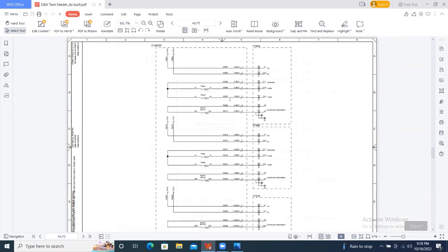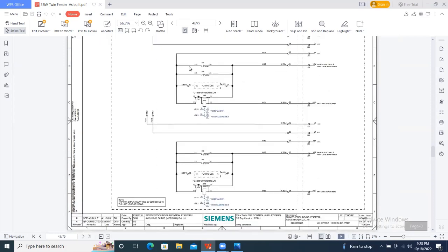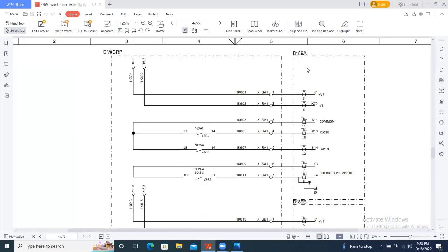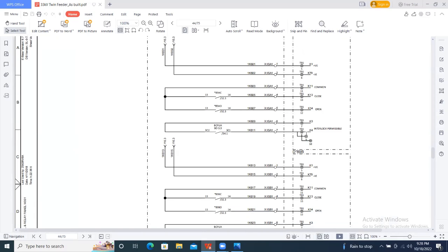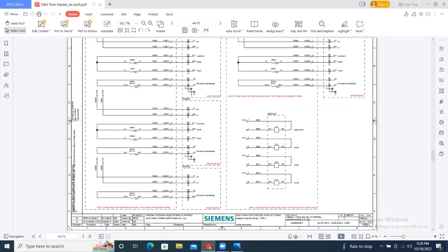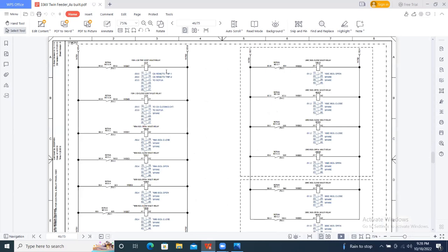And next, coming to the indications, suppose if you want to operate from isolator, that is a signal for the isolator, common. If you want to close, open, permissive, interlock from the BCU, soft logics for the isolators, for all the isolators and the switches. And the last pages will show you the contact multiplication relays.